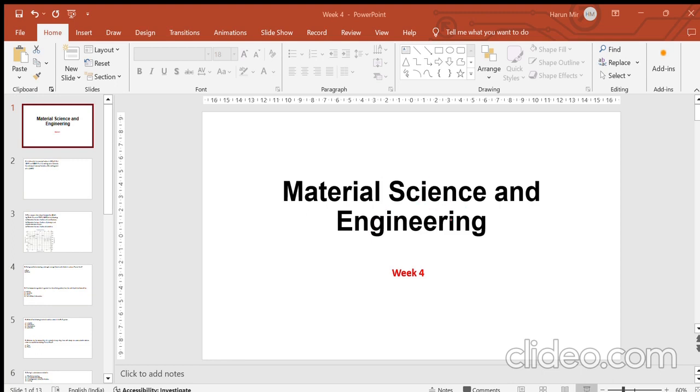Since we are in the alpha plus beta region, your final region is this 91.2. I'm sorry for the handwriting. So this is 25, this is 91.2, and then you have to see what this is. This is your solvus line. You take this composition as 8 weight percentage, because this is less than 10, so you can take this as 8 weight percentage, okay?